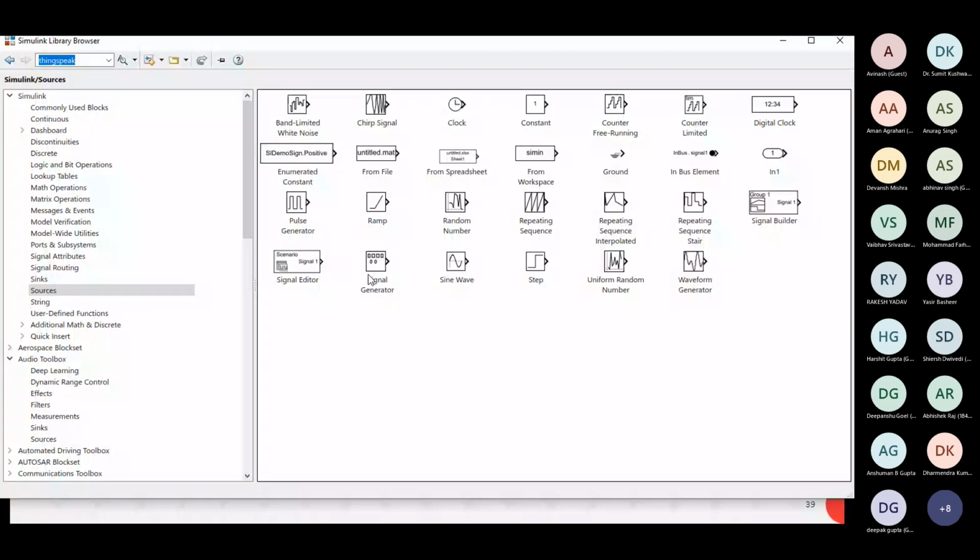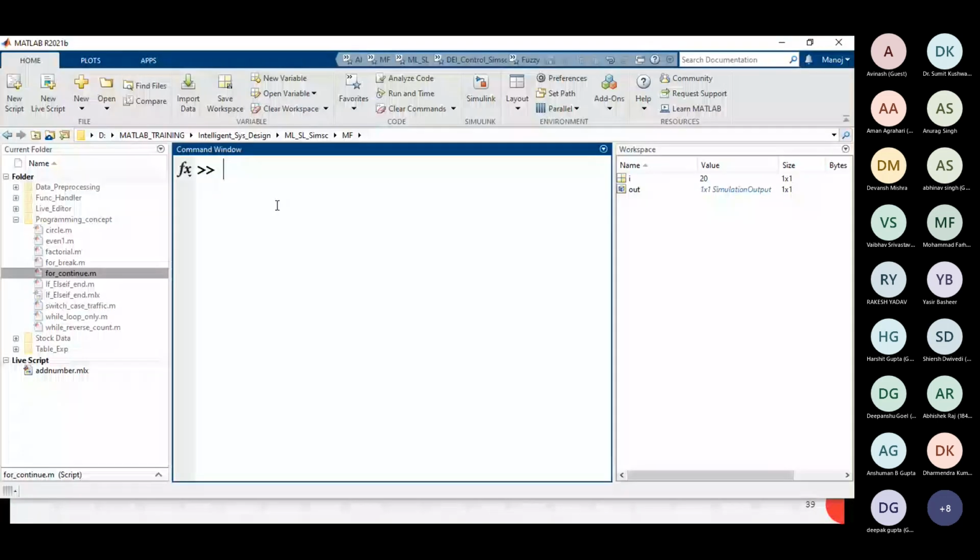As you know, if you have the system of an RLC circuit in your theory classes, you have applied some KVL, then you get some type of ODE equation from that. So basically, this system you are going to implement in Simulink using those equations. As you know, that equation may be dq by dt and so on. So for every system, you can create one type of ODE, and if you have the ODE with you, we can implement that ODE with the help of Simulink.